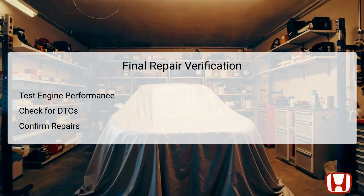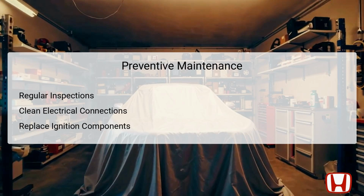Following the performance test, use a diagnostic scanner to check for any stored DTCs to confirm that the repair was successful. If no new codes appear, then the repairs can be considered complete. This verification process ensures that all issues have been addressed and that the vehicle is operating as intended, thereby restoring confidence in reliability.